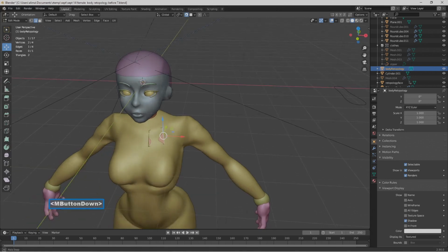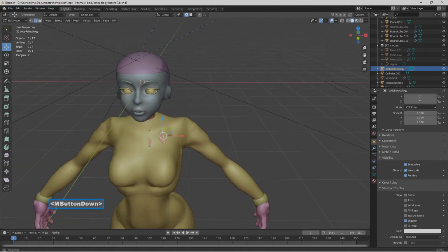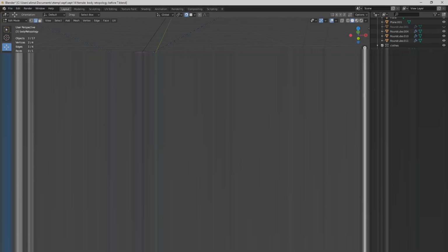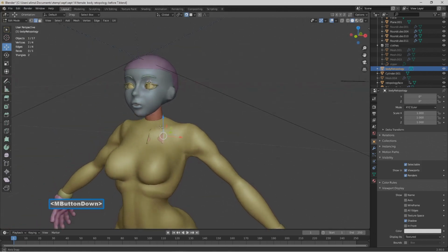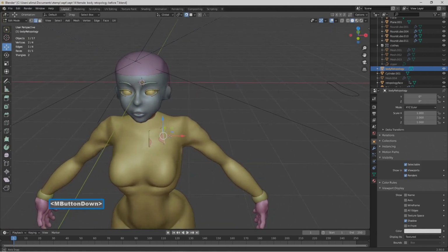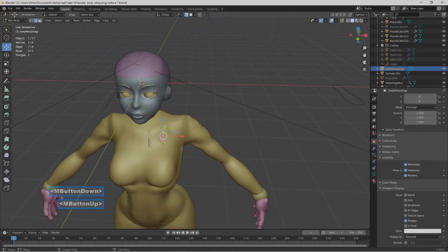So I've rotated the view, right? So when you're doing retopology, it's almost like you're aiming often where you want the topology to go. So when I rotate the view, I can adjust the angle. So I hold the middle mouse button to rotate to where I think about how I want the geometry to be extruded, as well as how I want it to be rotated. Once I have the angle, I line up my cursor, and then I'll hold control, like I'm doing now, and then I right click. So now I have my other geometry come out right to where I want it to be.